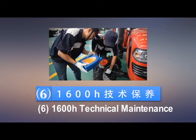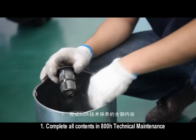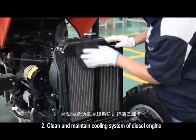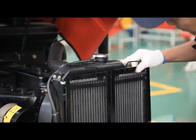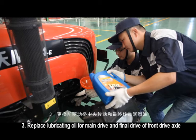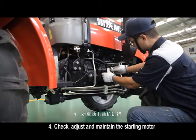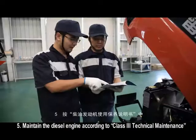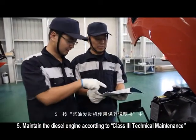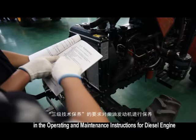6. 1,600-hour technical maintenance. 1. Complete all contents in 800-hour technical maintenance. 2. Clean and maintain the cooling system of the diesel engine. 3. Replace lubricating oil for the main drive and final drive of the front drive axle. 4. Check, adjust and maintain the starting motor. 5. Maintain the diesel engine according to Class 3 technical maintenance in the operating and maintenance instructions for the diesel engine.